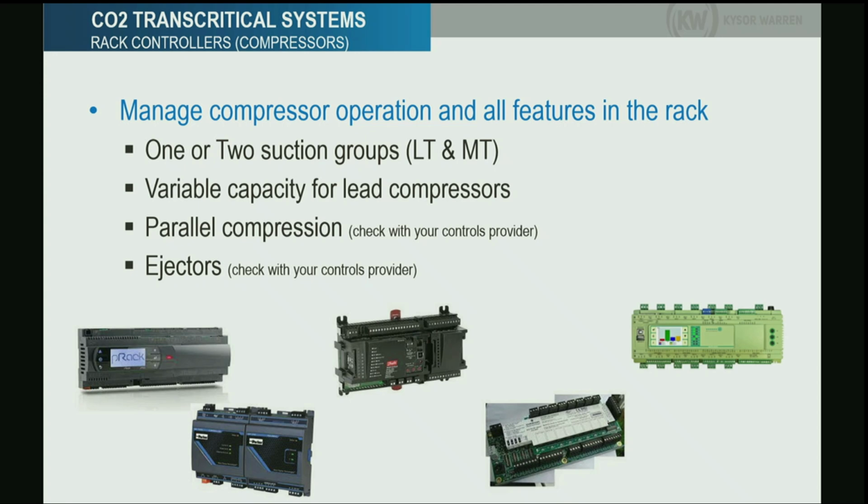Of course, if they can manage the store with a CO2 system, they have components for compressors. The only point here is that some of them have standalone components specifically for compressors. Some of them have everything integrated in one component, like this Carel component or that RDM. They manage the compressors and high pressure valve and flash gas bypass valve with the same module. They don't need separate modules. Some others need separate modules.